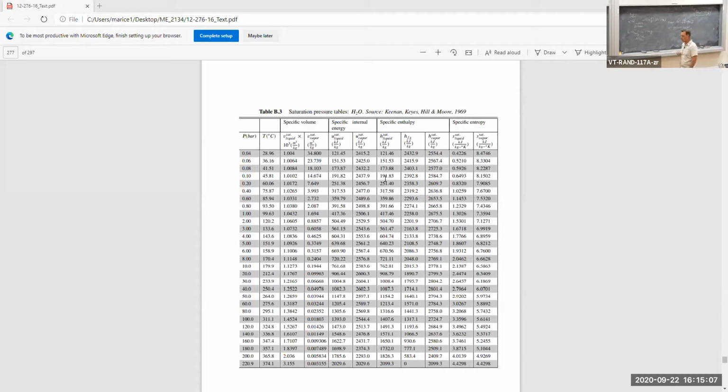Delta KE from 1 to 2 is negative because velocity going in is 80, velocity going out is 50 meters per second. So kinetic energy falls, so I got a negative 1.95 kilojoule per kilogram. All the units are the same. By the way, the kilograms cancel out with the kilogram in the M dot, and I get kilojoule per second, which is going to be a kilowatt.